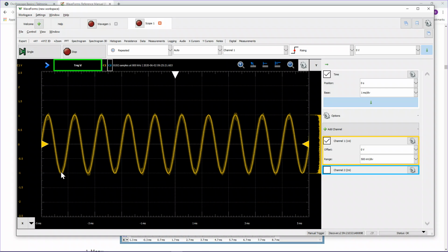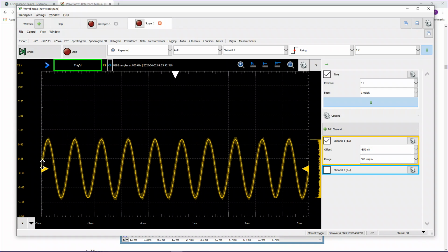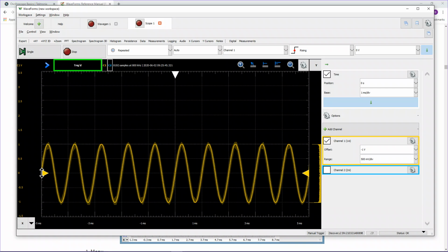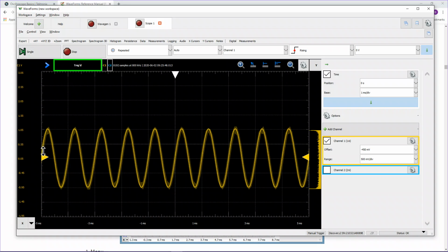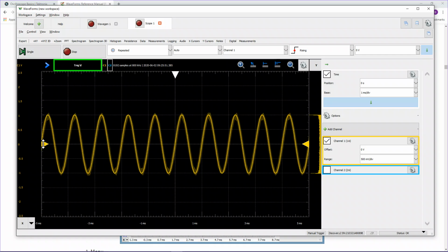There is a V peak measurement or explanation for a signal, and that is just setting a voltage to go in one direction, either positive or negative. There are some other measurements like RMS and different things like that when you're dealing with sine waves. That's another topic. So we can see this signal. It's pretty nice. And I can move the 0 point wherever I want on this scale. You always see me taking this 0 point and moving it right to a line. I sort of like it in the center, because I have an equal amount up above in the positive direction and an equal amount below in the negative direction. So that's a quick introduction to the voltage.